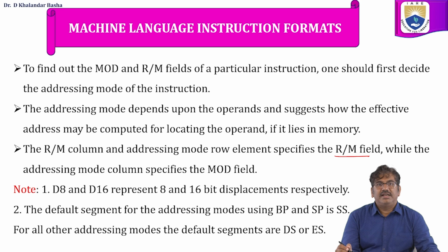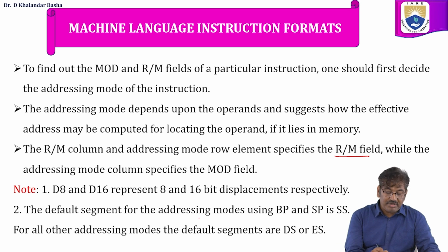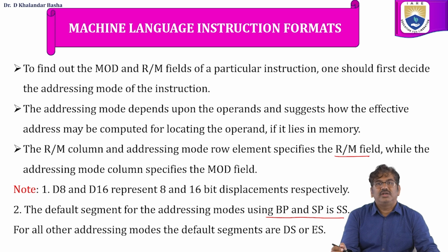So D8 and D16 represent 8-bit and 16-bit displacements respectively. The default segment for addressing modes using the base pointer and stack pointer is the stack segment. For other addressing modes, the default segments are the data segment and extra segment.